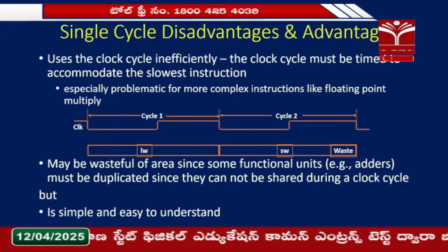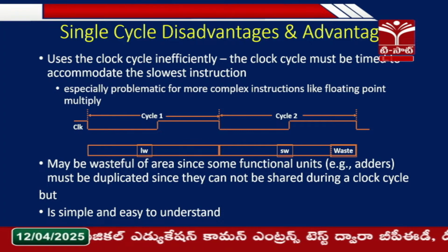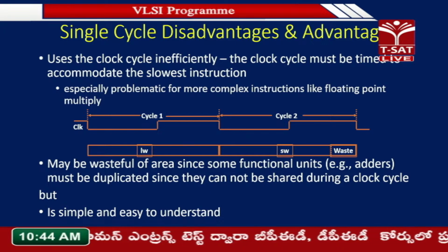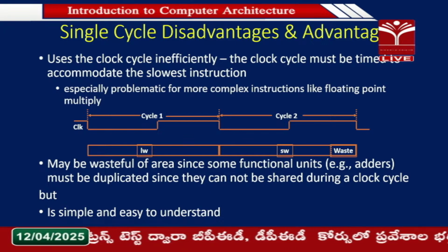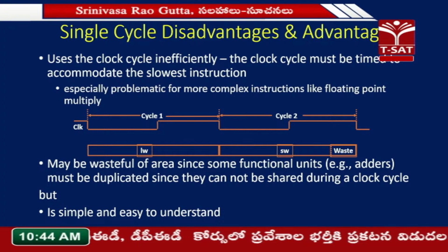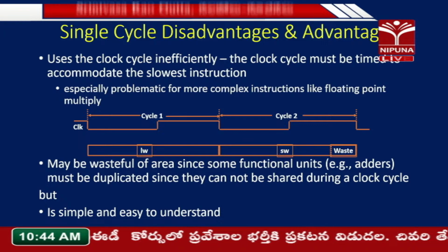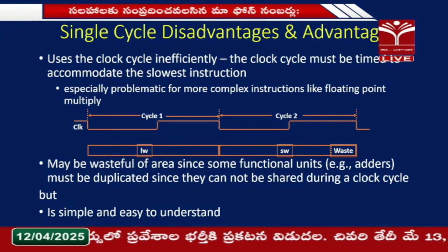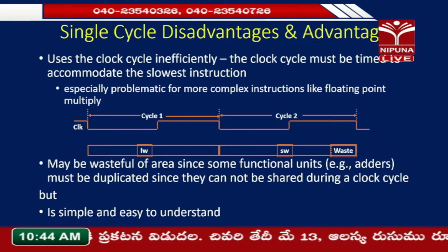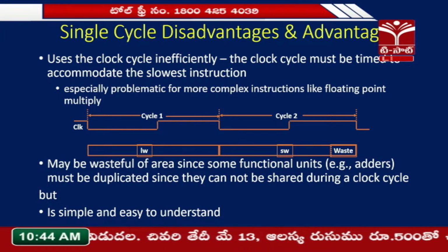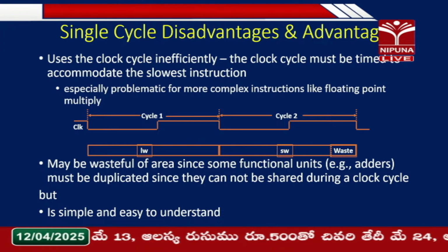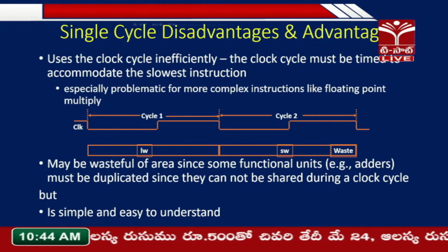And in this kind of single cycle design, which was there in the initial stages of the CPU being developed, there is a lot of wastage in terms of the clock cycle time, because not every instruction will use the same type of elements within the data path. They could be executing faster or slower.